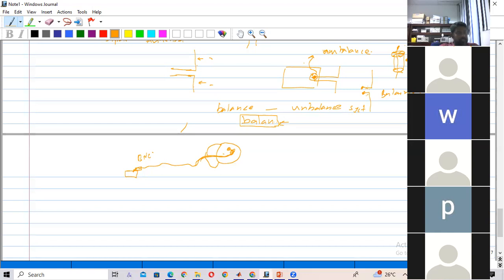So this is a balanced structure. This is also a balanced structure, so you can connect, no problem. And if it is PEO TV, actually the signals are not coming through the antenna. It is coming through an optical fiber cable. The optical connectivity comes directly to this router, then from the router to a decoder, then from the decoder to a TV, you can connect. So here also there is no concern with balanced to unbalanced.